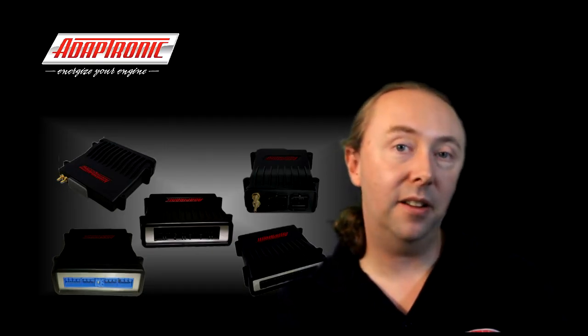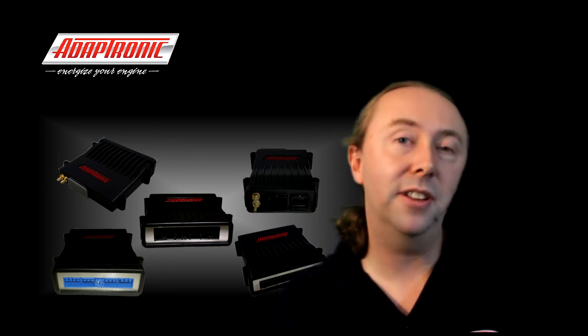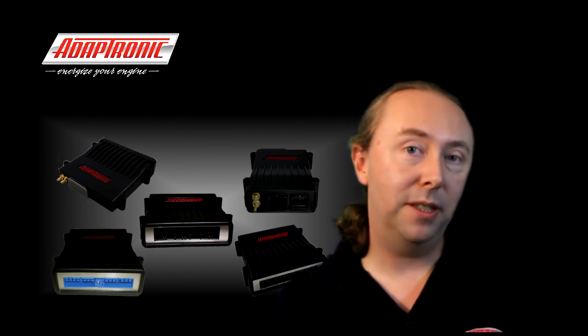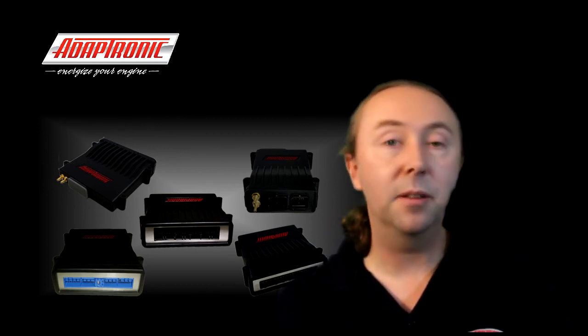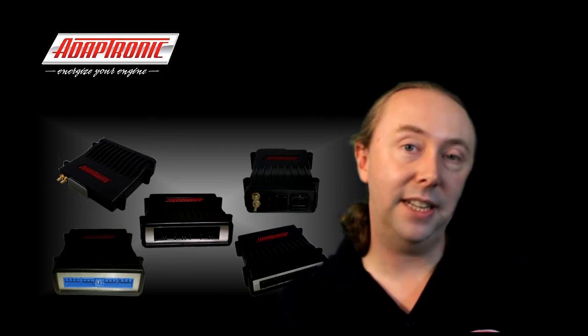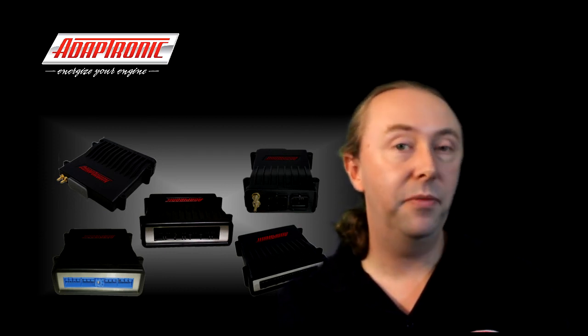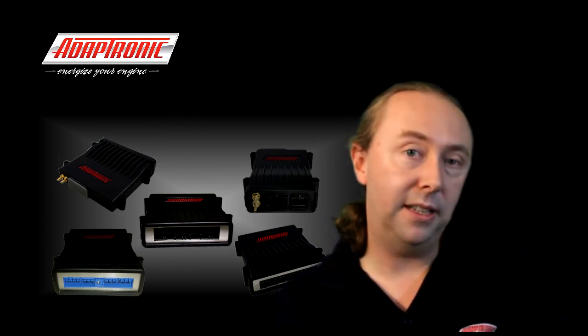In most cases, the idle valve will bypass the throttle body, and it's actually called a bypass air control valve by some manufacturers. But in some cases, the idle valve puts air into the intake manifold but gets air from the airbox, which means that when the engine's on boost, that idle valve becomes a boost leak. So if you enable the close idle on boost function, then that will close the idle valve as far as possible while the engine's on boost.